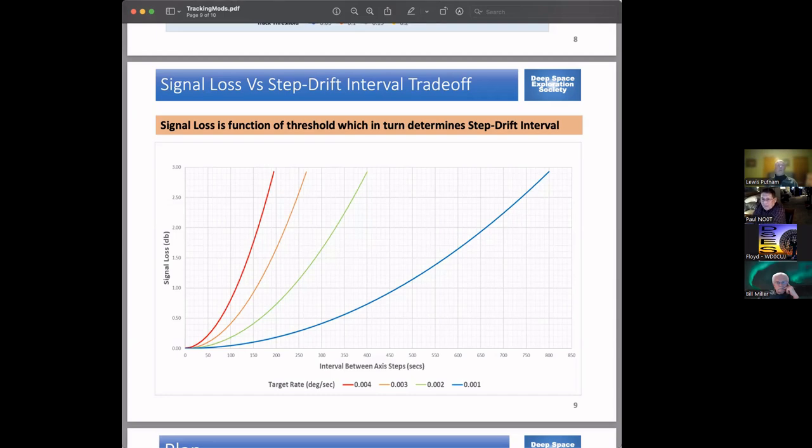I think we could run the azimuth close to continuous, but right from our early testing, it looked like the slowest it would run at was around 0.01 or 0.02 degrees per second, which is still above the sidereal rates. I haven't gone back and re-verified that, but at the time, everybody thought it was probably stiction. I don't know if that's really what it was or not.